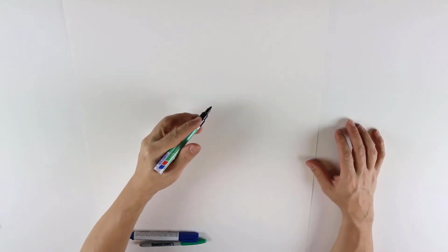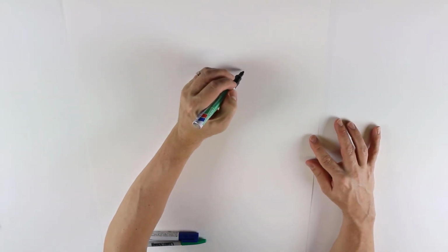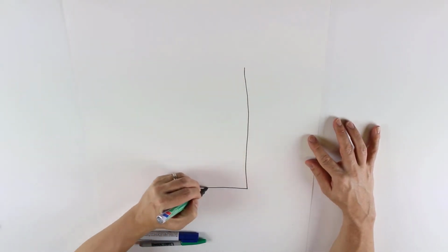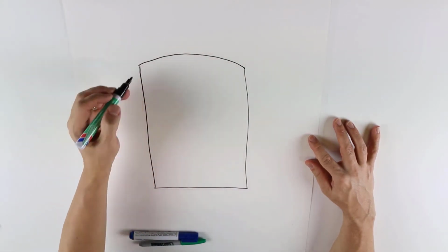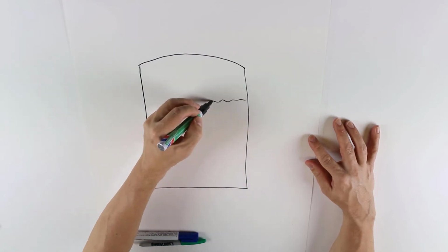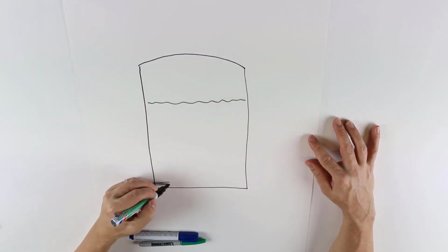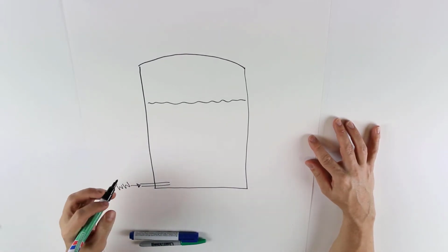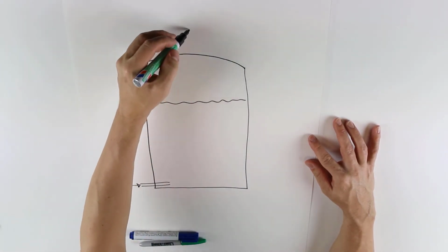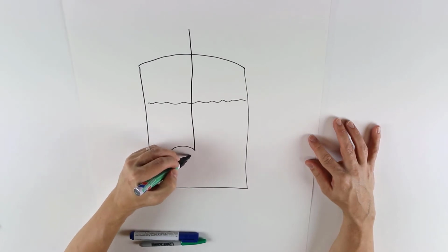The simplest reactor design for anaerobic digestion is the so-called CSTR, the continuous stirred tank reactor. It's nothing more than a simple reactor in which we bring our influent or wastewater, and it comes into a large tank that is typically stirred.